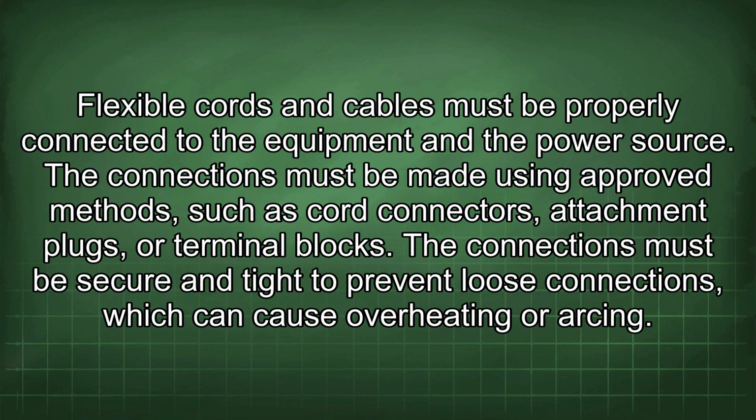Flexible cords and cables must be properly connected to the equipment and the power source. The connections must be made using approved methods such as cord connectors, attachment plugs, or terminal blocks. The connections must be secure and tight to prevent loose connections which can cause overheating or arcing.